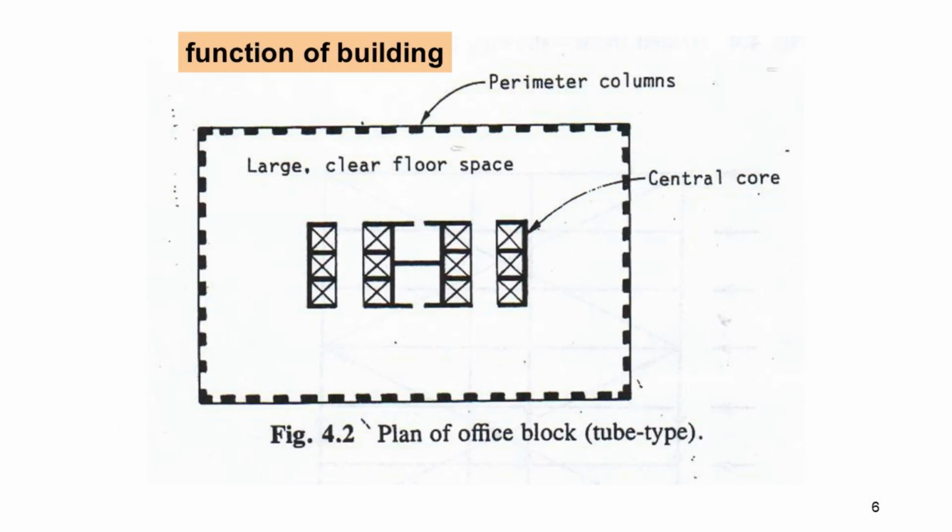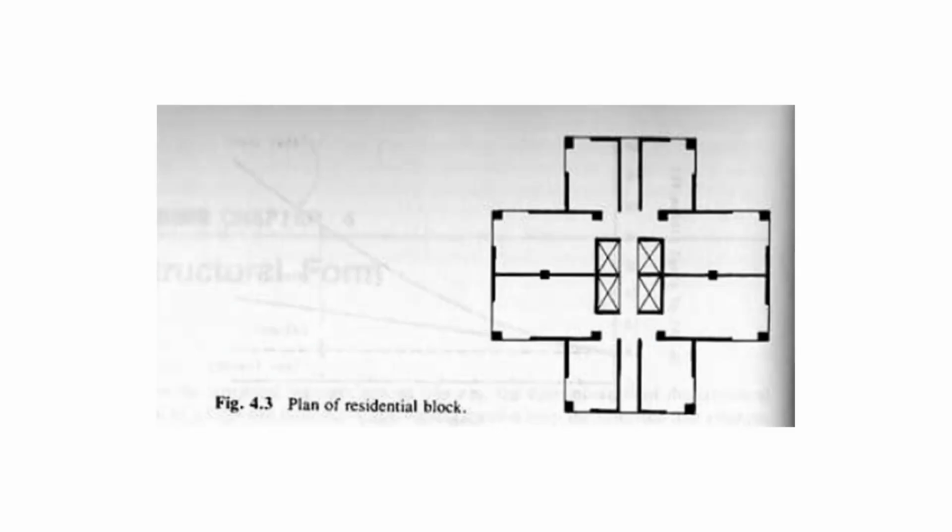Another thing that you must consider is the function of the building. For instance, an office building requires open space, column-free areas, like partitions. Services in the ceiling cause a story height greater than 3.5 meters. On the other hand, a residential building requires continuous vertical columns and walls, repetitive corridors, in which the story height is greater than 2.7 meters. By identifying the building's function and material used, it will provide architects and engineers a comprehensive view on the planning and design aspects.